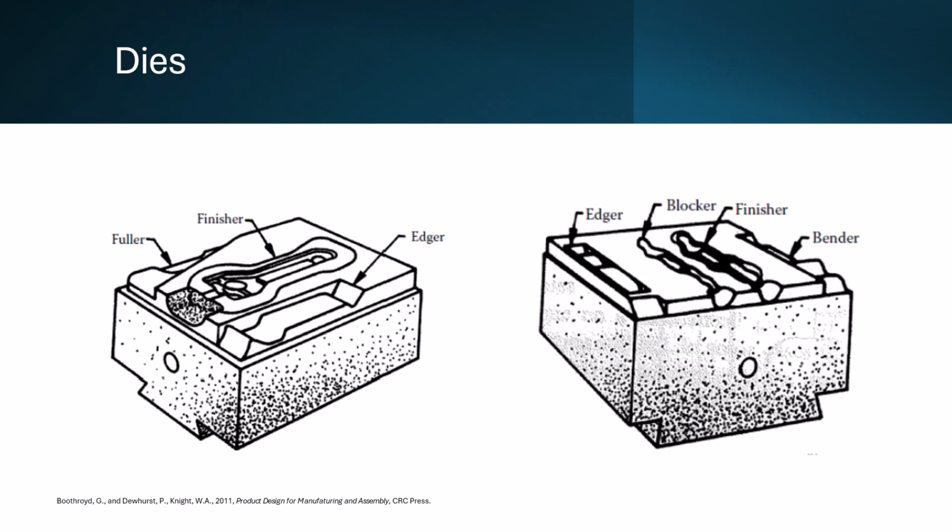This brings us to dies. Dies are used to shape the material in each forging step. If the parts are small enough, several or all of the preform and finishing impressions may be incorporated into one die. If this is done, they must be arranged to minimize the size of the die while ensuring they are adequately spaced. Another factor in die design is the parting line. Flat, simple parting lines are preferred, and if the parting line becomes complicated, die locks may be added to prevent mismatch.